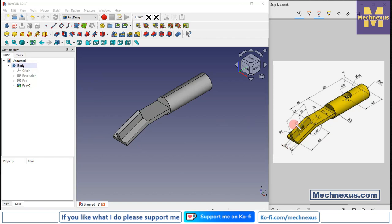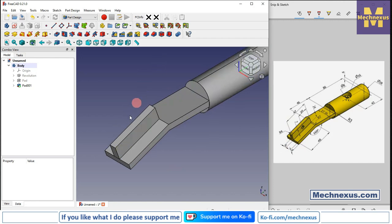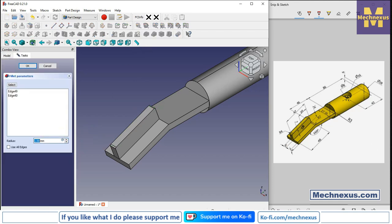Now here is a 2 radius of R4. So we will press Ctrl and select this 2 radius and click on the fillet and provide the value of 4 mm. Click on OK.